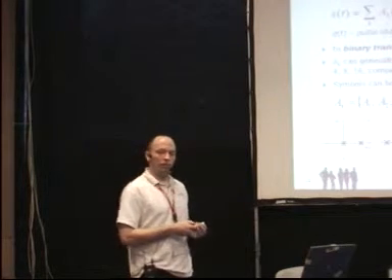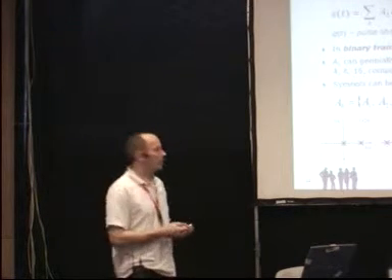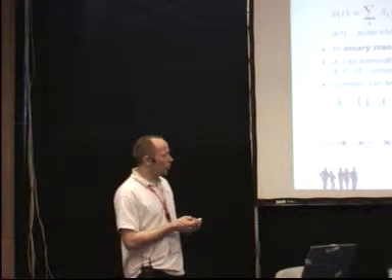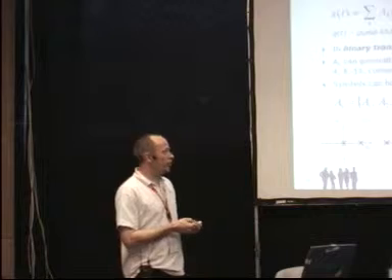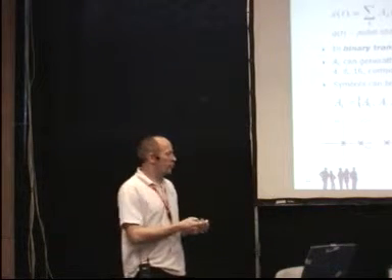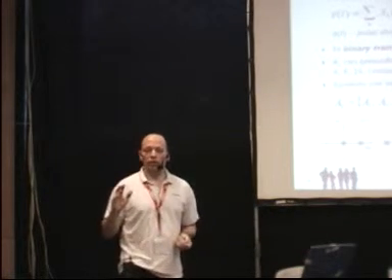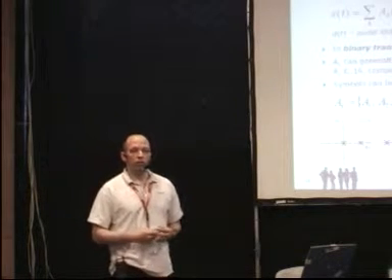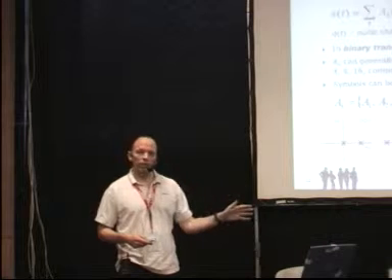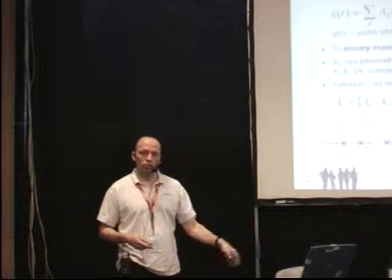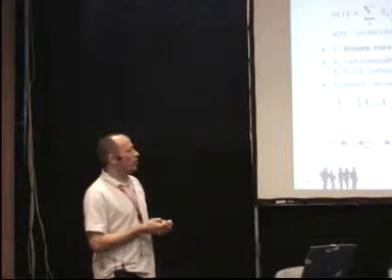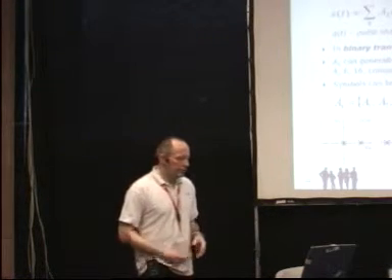Then one of the candidates for 40 gig that is massively discussed today is differential quaternary phase shift keying. So here we have 4 symbols, with 4 states of the symbol. So with one symbol I can obviously transmit 2 bits, effectively decreasing the baud rate on the fiber to 20 gigabaud. And there are other candidates, 8 DPSK, 16 DPSK, etc.